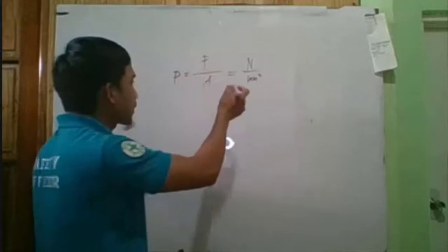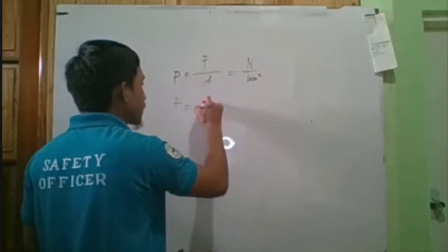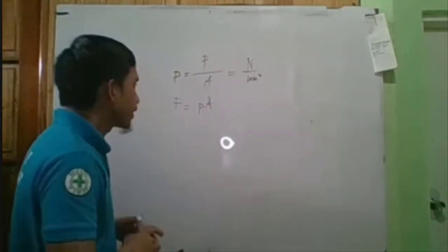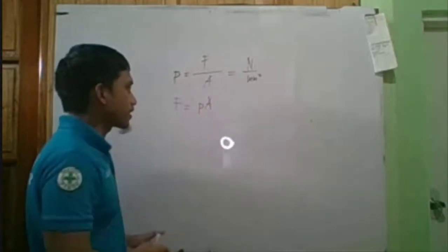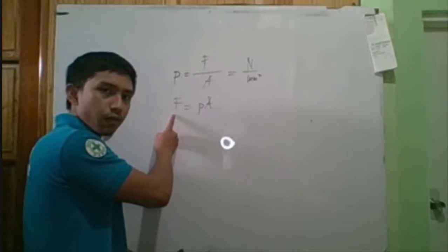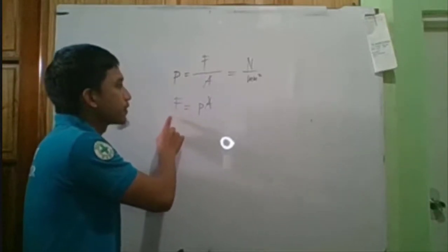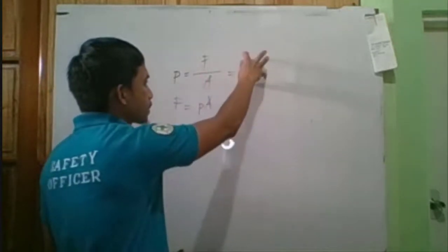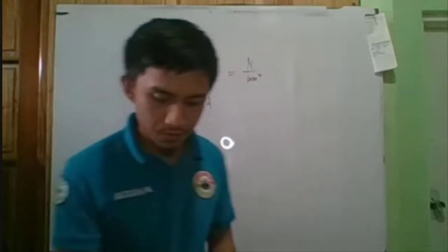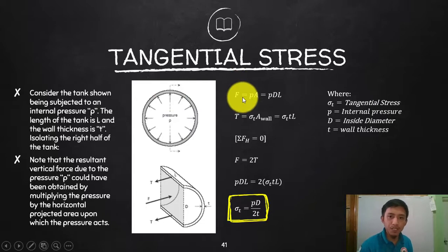I can rearrange this one, and then you will have there the force F equals the pressure p times the area of whatever is under that force F. That area will be the one to be converted into a single force, or concentrated force F. So that area, if you are using MPa, you need to have that area in millimeters. That is just unit manipulation. So again, that is how we ended up here with F, which is p times A.